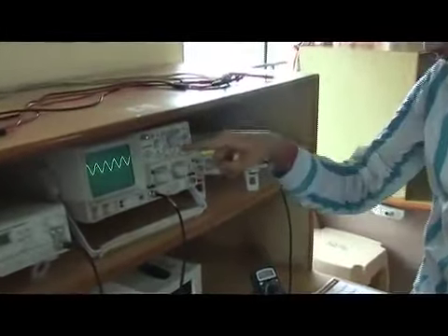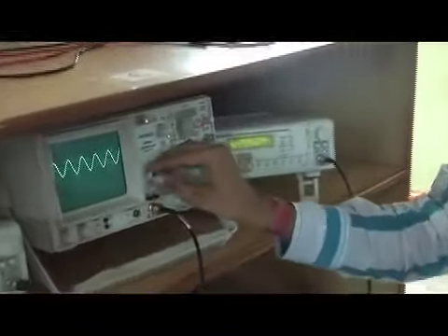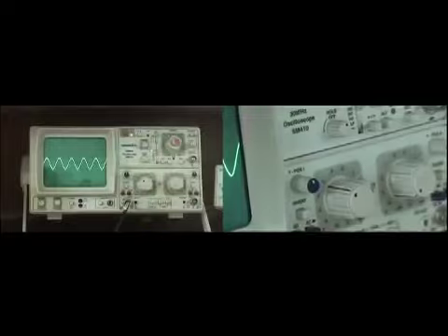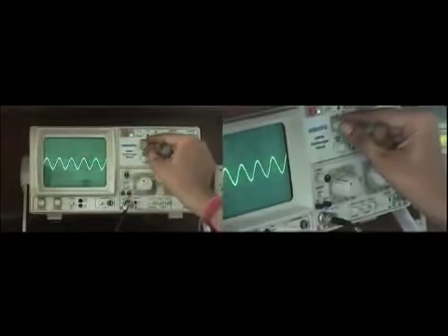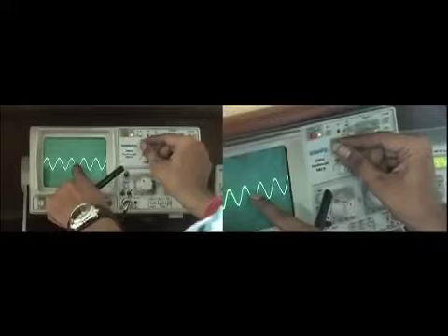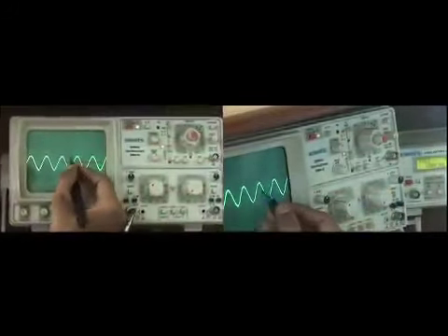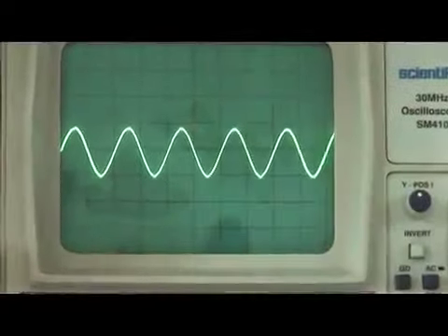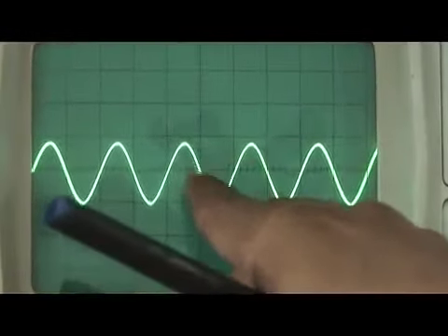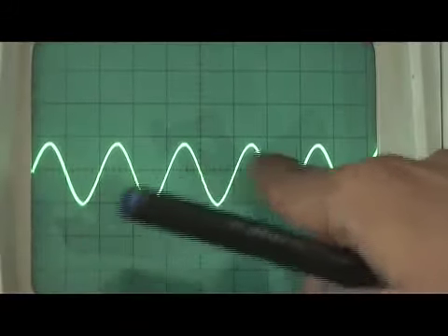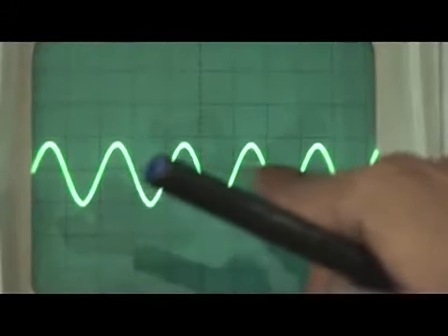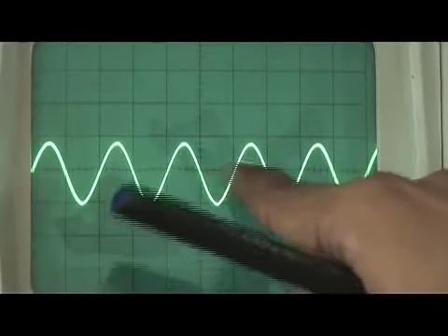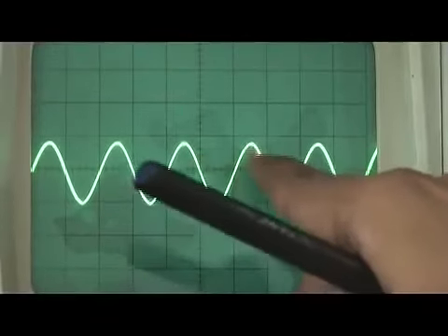Next we move to how to calculate the frequency. Again, make it ground, bring the line to the center, release the ground, and set this y-axis in such a way that you can easily count one cycle. If I set it here, from this point to here is my one complete cycle. How many blocks does it require? It requires almost 2, so let us take it as 2. So it is 1 block, 2 blocks. To complete one cycle it requires 2 blocks.